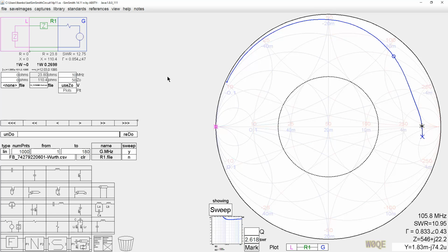Ferrite beads are notoriously nonlinear. Now, I said in an earlier video that the components had to be linear time invariant. Well, the ferrite bead we're going to call linear, but it's linear at a frequency. As we vary frequency, every time we vary frequency, it's a new problem. So being a new problem means it can still be linear. It has a value at 10 megahertz of this value. Yeah, I didn't quite get 10 megahertz there, but it has a value at 15.51 megahertz of that value. And by the time you get up here, it's got a value. This is what's known as a 600 ohm bead. It has approximately 600 ohms of impedance at 100 megahertz, is the way it's spec'd.